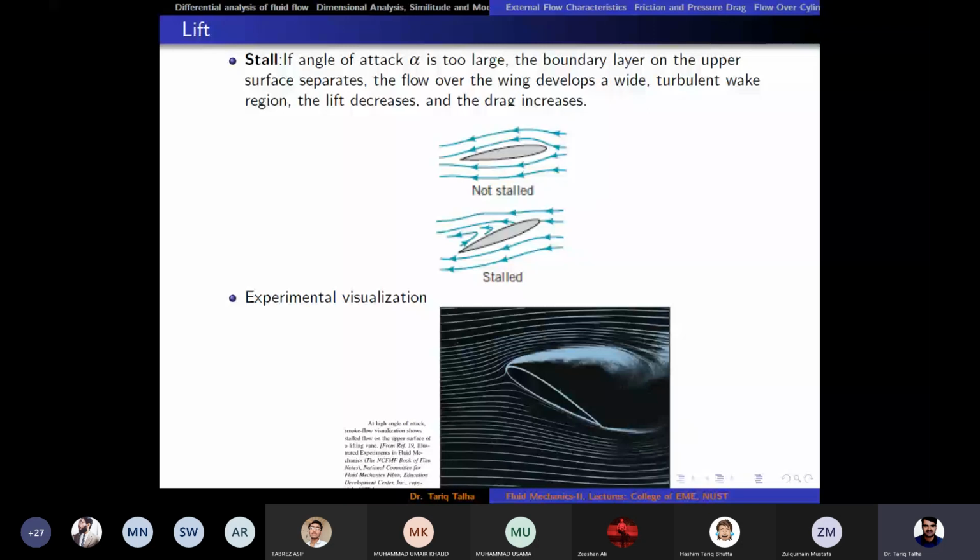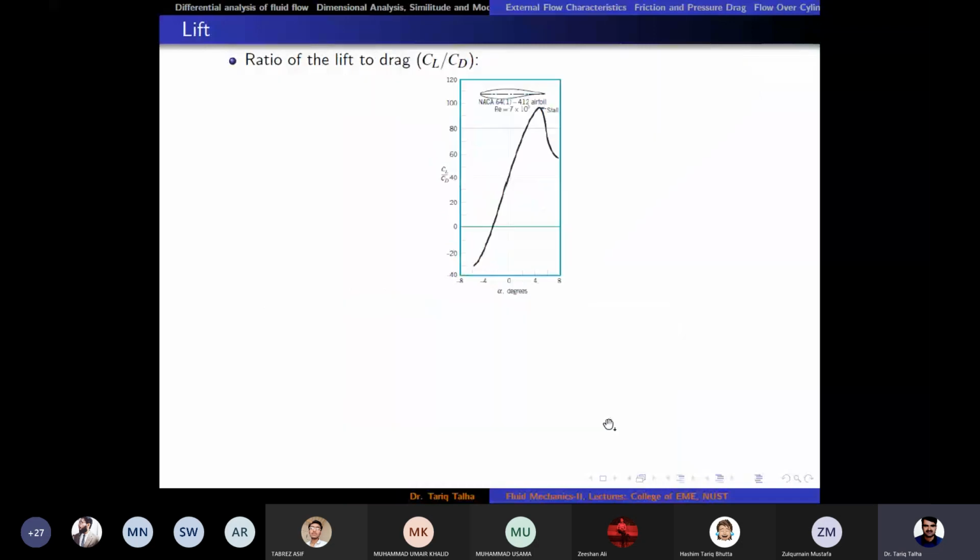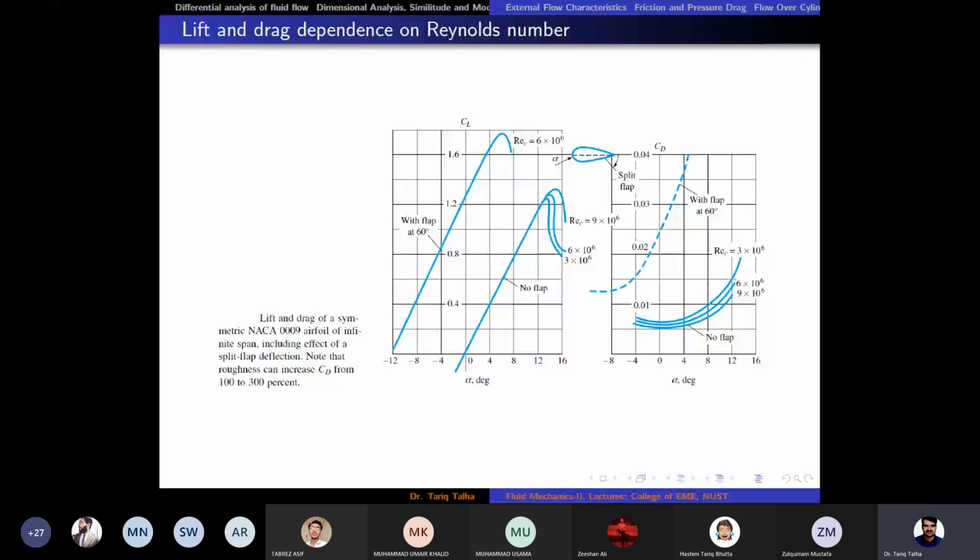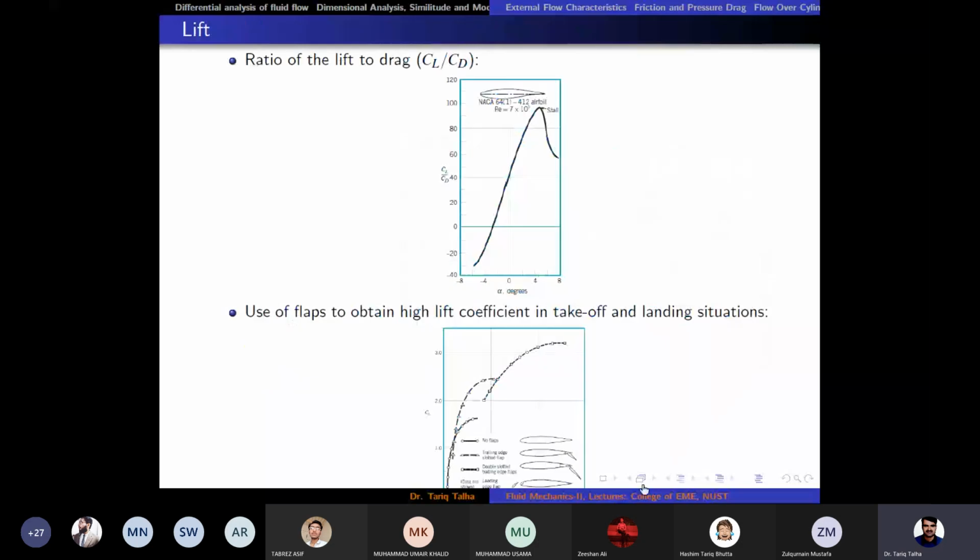And then there is another thing, if you ever travel on an aeroplane. There are some kind of flaps on the trailing edge. Those flaps are used to create additional lift, right? If I show you the figure for that, in this you can see some movable flaps on the trailing edge. If we make it more downward, there would be more pressure on the lower side. It means that the lift force would be more.